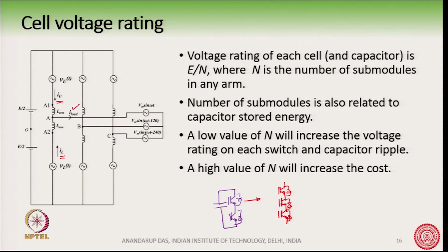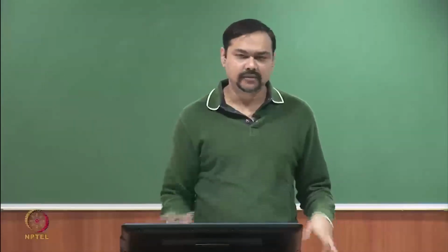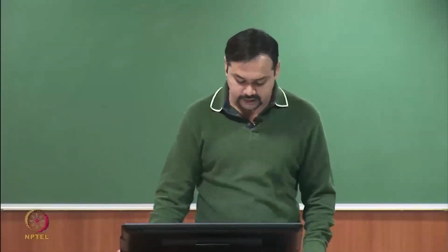Now, the voltage produced by this converter is almost like a sine wave. So, for the load current, we can assume that it is almost a perfect sine wave, and can be represented by the equation I load equal to I max sine omega t minus phi, a sinusoidal function.